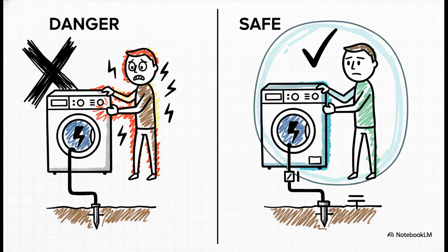This is exactly why you absolutely must ensure that advanced hybrid topologies feature an internal automatic ground signal relay. The moment the grid drops, this relay closes, building a localized temporary neutral earth bond right at the property. This guarantees that your protective residual current devices, your RCDs, still trip correctly and, most importantly, safely protect human life.